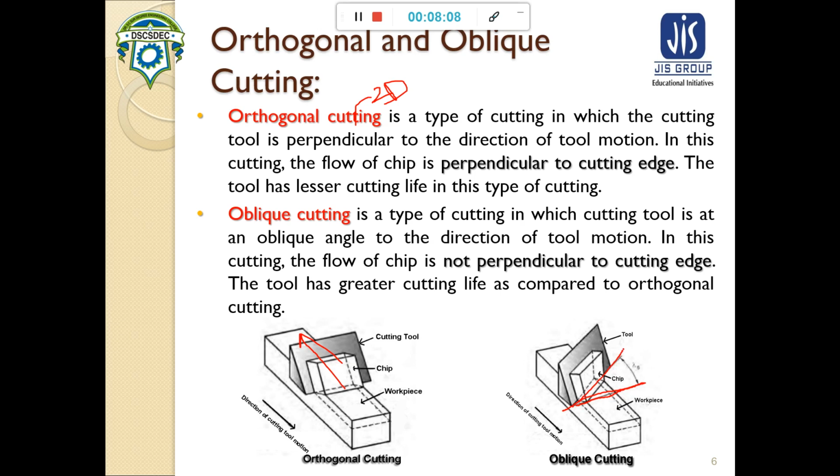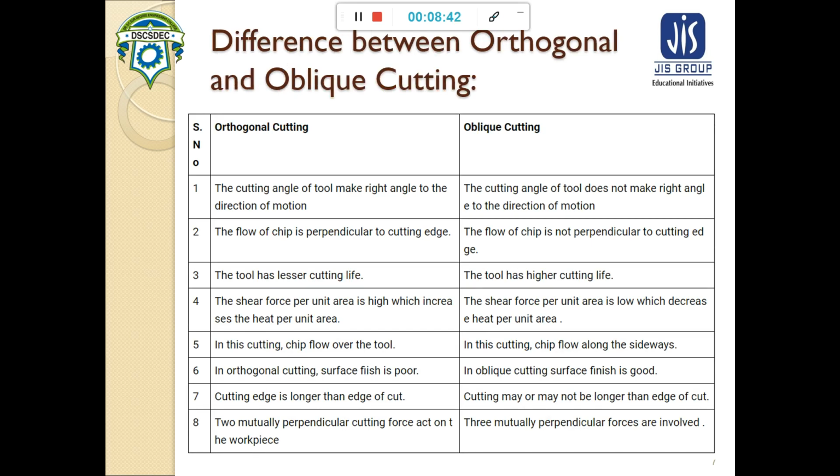The cutting tool is not placed perpendicular to the tool motion, so it is at an angle. The flow of chip is not perpendicular to the cutting edge, and the oblique tool has greater cutting life as compared to the orthogonal tool. This oblique cutting operation is known as a three-dimensional operation.